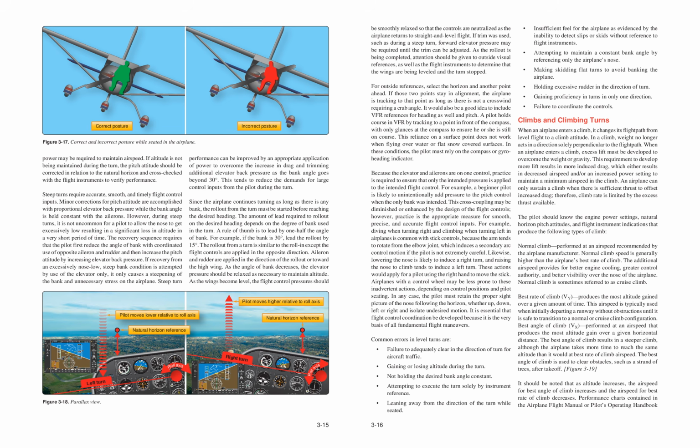If recovery from an excessively nose-low, steep bank condition is attempted by use of the elevator only, it only causes a steepening of the bank and unnecessary stress on the airplane. Steep turn performance can be improved by an appropriate application of power to overcome the increase in drag and trimming additional elevator back pressure as the bank angle goes beyond 30 degrees. This tends to reduce the demands for large control inputs from the pilot during the turn.